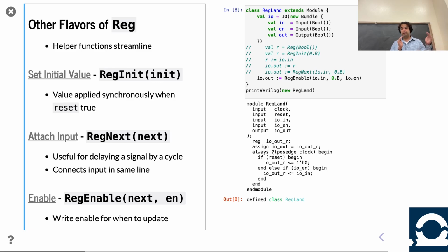That would be a great time to use a black box. You make this Chisel black box where you can have Verilog inside. Inside that Verilog black box, you can put whatever code you use to instantiate your magic registers, probably going to some library and instantiating it directly with structural Verilog. And then at the Chisel level, you can just use that Chisel module.